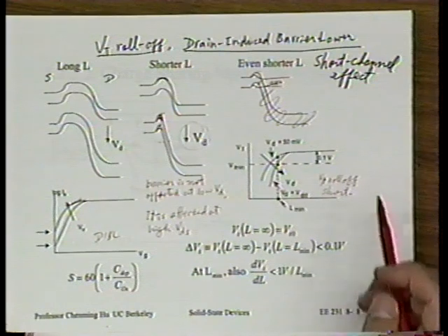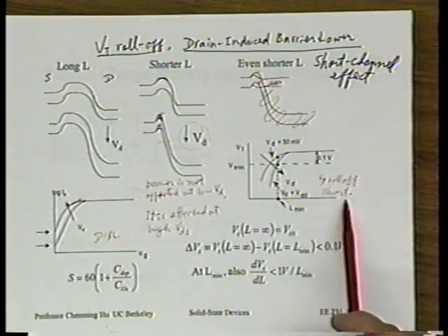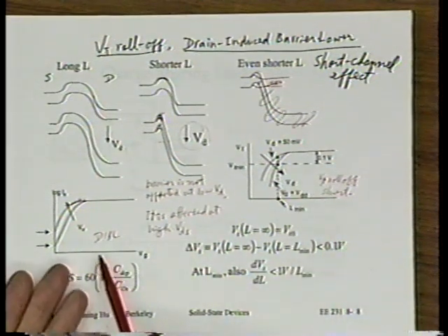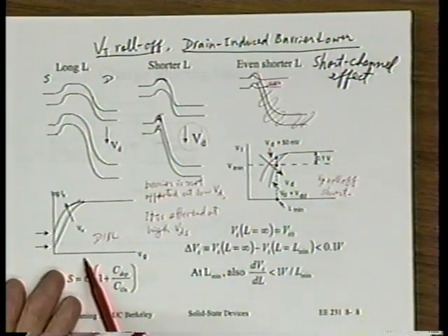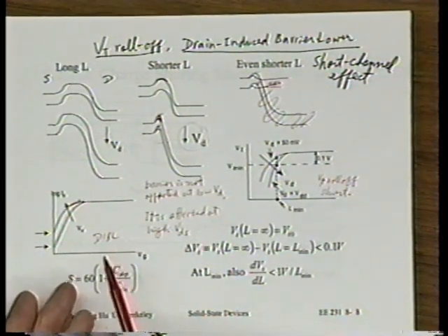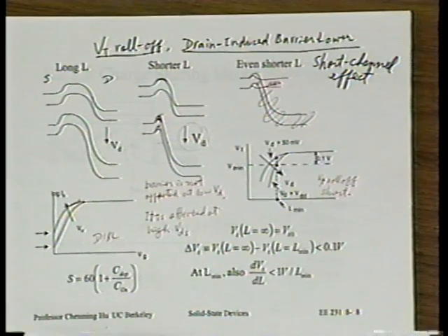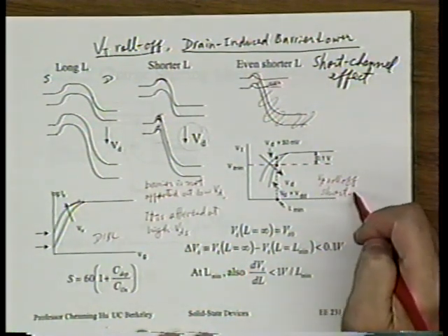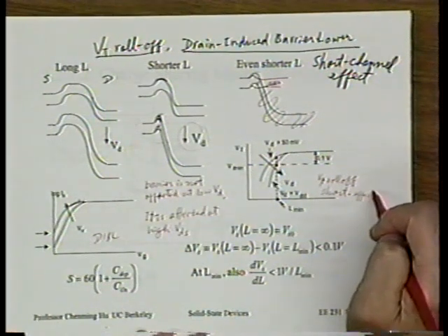But you can see why some people want to do that because this has to do with channel length, L, the short channel effect. But this is a strong function of channel length too. Very strong function, in the sense that if I make channel length a little larger, DIBL goes away. So how can you say DIBL itself is not a short channel effect? So sometimes the terminology can be confusing. Different people use it to mean different things, all right?